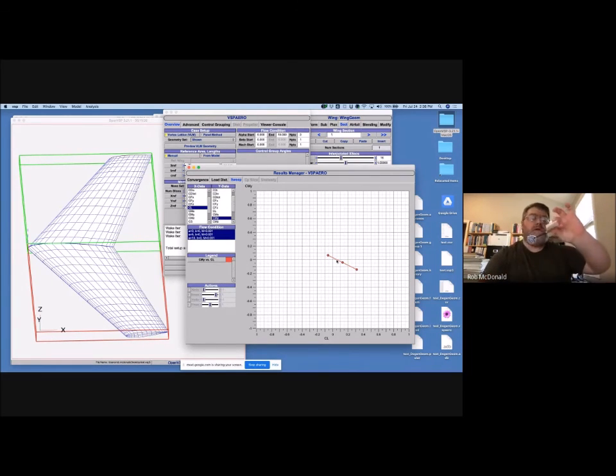And so by varying that pitch, by varying CL, that determines what speed that airplane's going to fly at, not the throttle. And then when you add more throttle, what that'll do is at the same speed, that'll cause you to climb or to descend. And so if you want to stay at the same altitude, then you adjust the throttle just right until your rate of climb is 0. So you could really think, right, most of an airplane's flight, think about flying across the country to go visit grandma or something, right? You're in a 737 and for 4 hours you fly over Oklahoma or someplace, right?